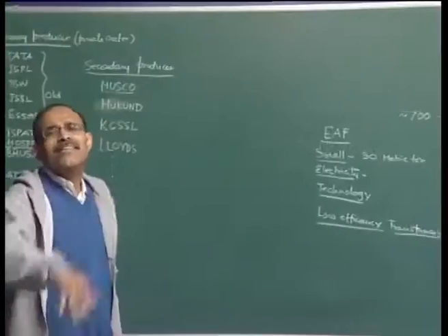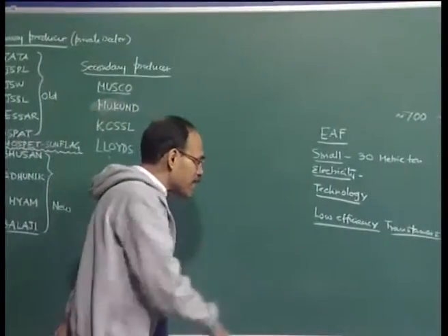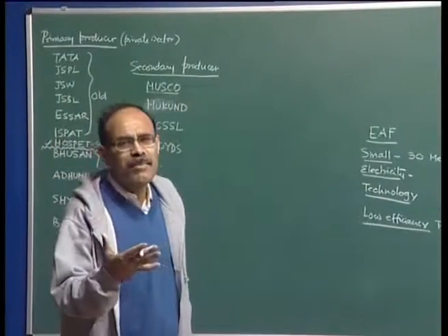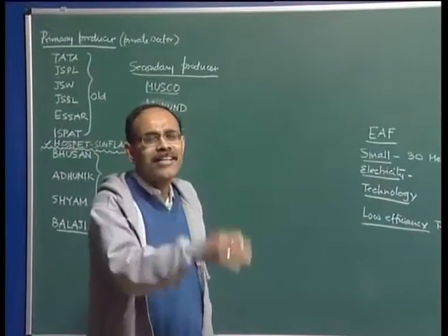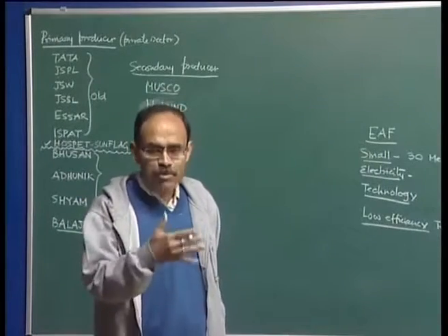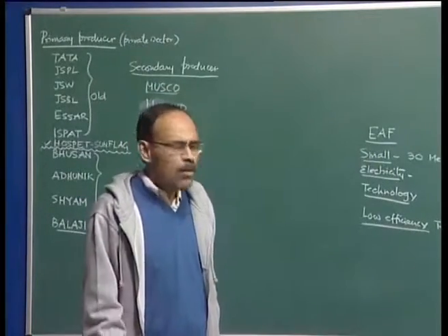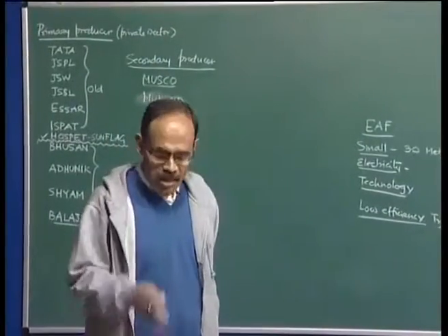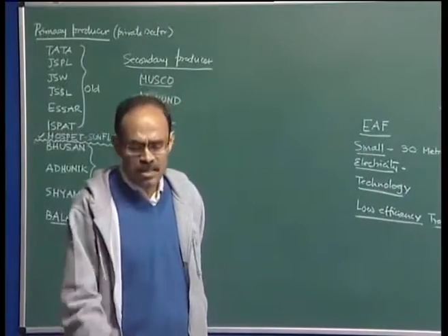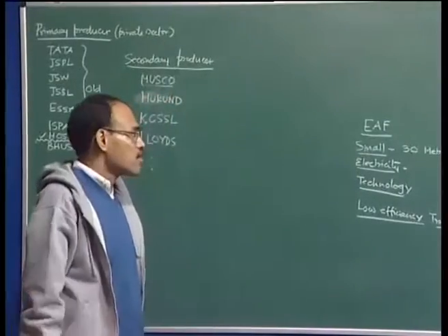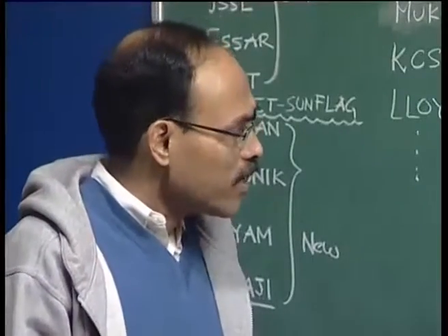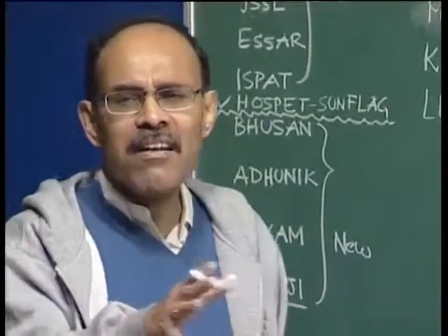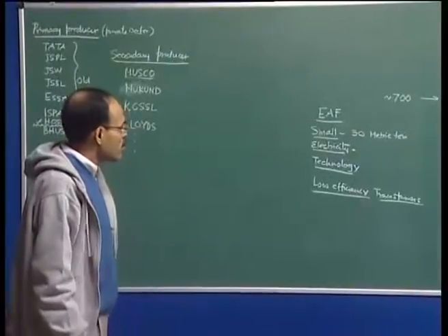So the tap to tap time is really high because you require melting and refining. Today still, if you go for electric arc furnace steel making, they are making life of integrated steel makers miserable in terms of providing the right kind of competition, because so many developments have taken place in electric arc furnaces, which you may have done, starting from CoJet technology, submerged gas injection, fume hood analysis, good process control, good end carbon determination. On every front, electric arc furnace has undergone a revolution as far as steel making is concerned.